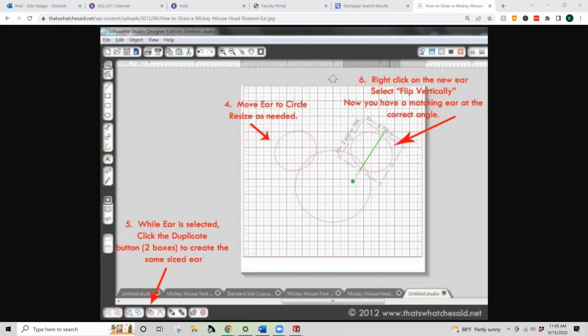We need to pay attention where these two intersect, because that gives us the point we're interested in. I'll change color so we can see where we measure. So the center line for this guy, if you're trying to figure out on a drawing where it is, you manually need to draw a line. It's good practice just to do that, so I'll do that in green as well. So green's how we're finding our center lines.